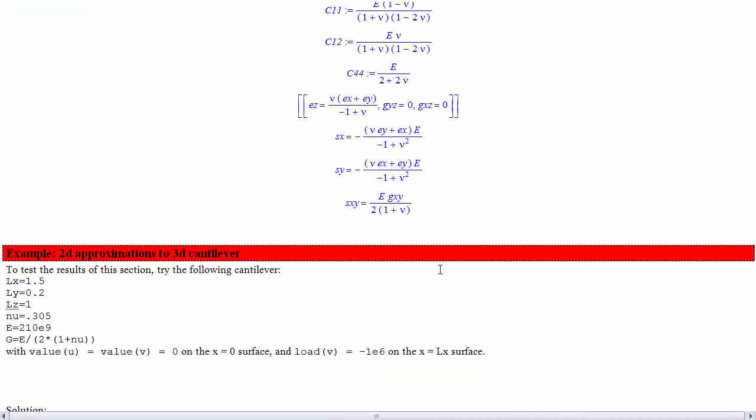All right, so let's look at these 2D approximations to a 3D cantilever. Let's first try this cantilever with a fixed load. So we're not going to be doing a resonant mode type thing. We're just going to be looking at cantilever displacement and see if you can apply appropriate boundary conditions to this cantilever by building it in 3D and compare with using these 2-dimensional approximations here.